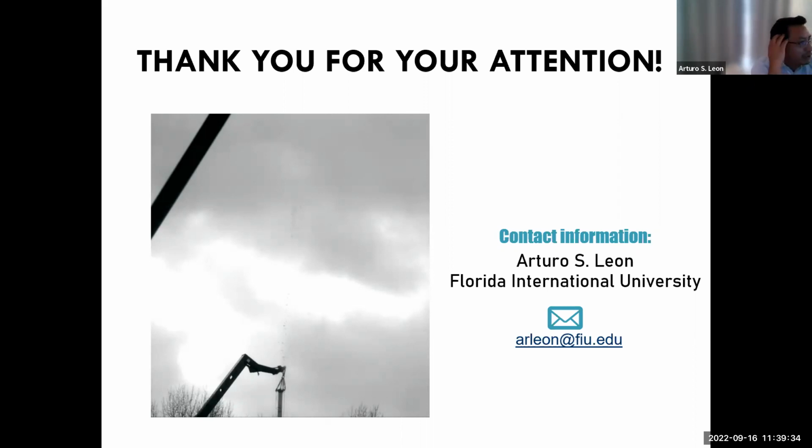In that case, you might produce flooding upstream of the manhole. That's actually what happened in Chicago. The diameter of the manhole was too small, so a lot of the water would flood the area surrounding the pumping station. So we asked to increase the diameter of the shaft. That's one issue.